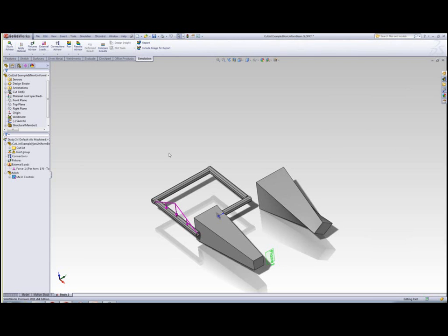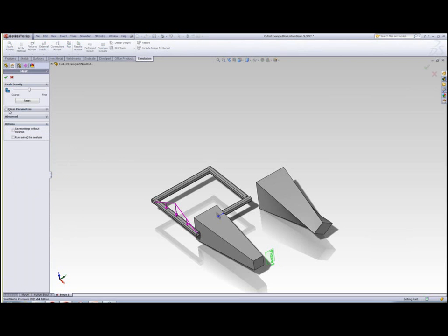Also, another thing I want to point out with meshes is the default mesher has changed. So let me talk about this. It's nothing to be afraid of. It's actually quite good. If I go into my mesh and do a create mesh, under mesh parameters, we still have our standard mesh, which is what most of us who have been using the software for a while are used to. It does a standard mesh, and it uniformly applies nodes and creates elements amongst the geometry as it is.